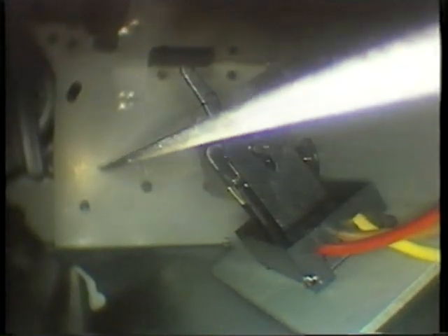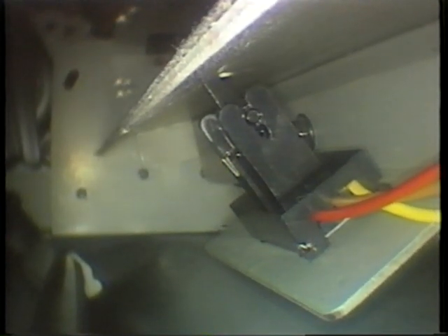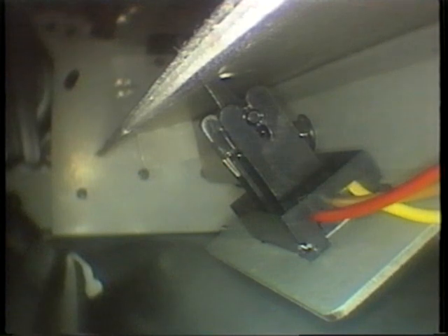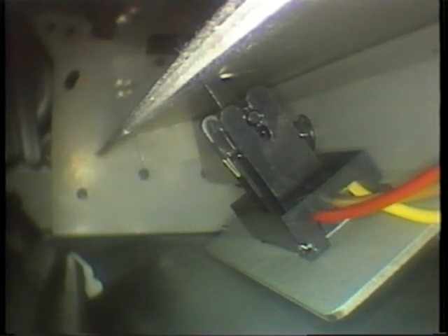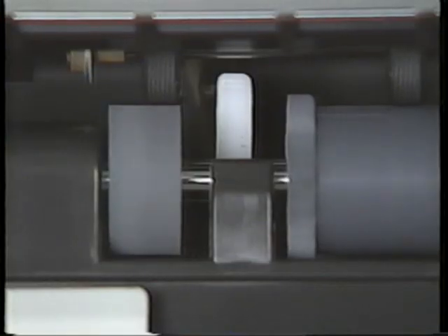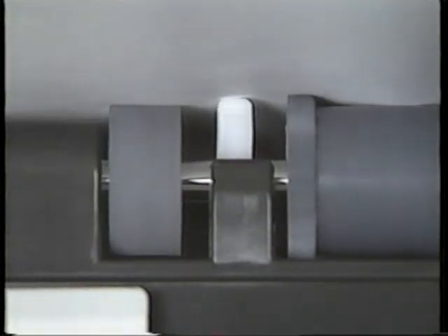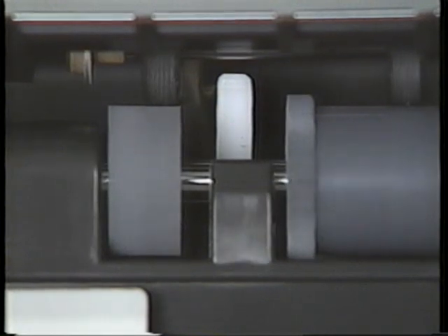This sort of accurate control is possible not only because of clutches and solenoids, but also because of sensors in the paper path. Paper path sensors are often hybrids with mechanical and photoelectric components. Many use a small actuator lever, which every passing sheet pushes down, raising the lower portion out of a photointerrupter. They're positioned to let the control system know when a sheet of paper has reached certain key locations, so that other systems can be activated according to the proper timing.